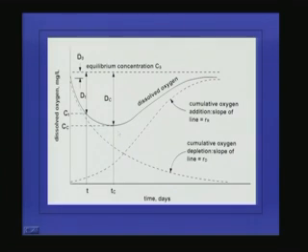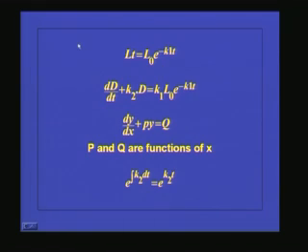We will be able to predict the critical deficit, the location where it is occurring, and the corresponding dissolved oxygen concentration. And this line shows the saturation oxygen concentration. That means at a particular temperature, this is the maximum dissolved oxygen concentration the stream can have. So that is Cs. So now we will see the derivation of the dissolved oxygen model.